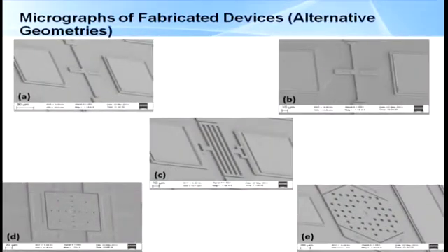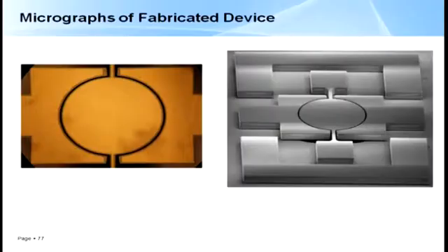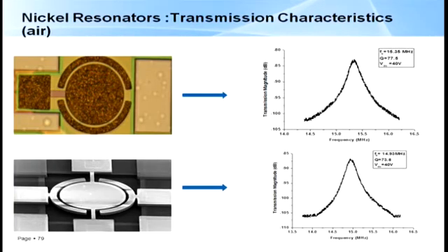Now, look at the resonator characteristics here. These are some very exotic structures fabricated by SOI, metal and silicon processes. This is called the metal resonator, and this is very interesting. This is thick silicon oxide, that means it is the SOI or silicon on insulator resonator structure, which can be used as a filter, or as a clock generator. And that finally gives you the kind of quality factor you can achieve.